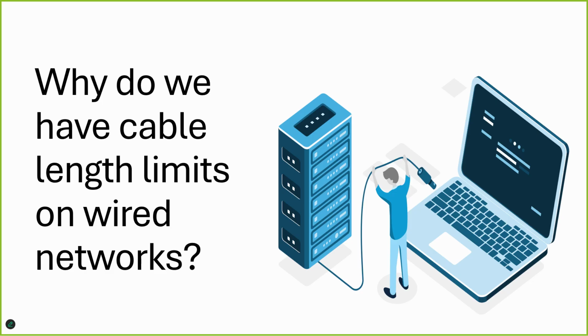operations and troubleshooting and design, because what it comes down to is everything attenuates no matter what medium it is traversing. Now, it will attenuate differently as it's utilizing a different kind of medium. So in other words, signals will attenuate differently on a cable or on fiber with optical communications or on wireless. It'll attenuate differently. In other words, attenuate a different amount at a different distance, right? But there's still attenuation.